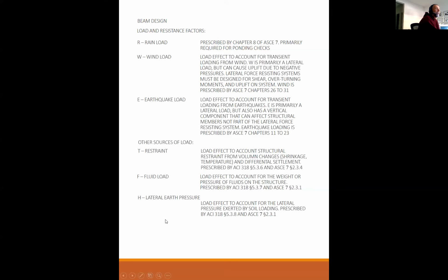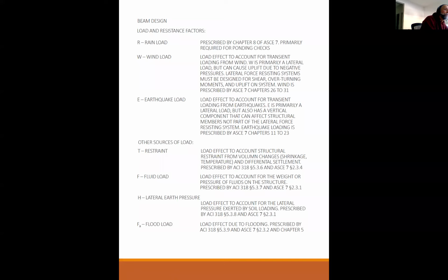H stands for lateral earth pressure, load effect to account for lateral pressure exerted by soil, prescribed by ACI and ASCE 7. Think of retaining walls. This would be the main structural element that you see all the time that has lateral earth pressure, retaining walls. F sub A is a flood load effect due to flooding, prescribed by ACI and ASCE 7.